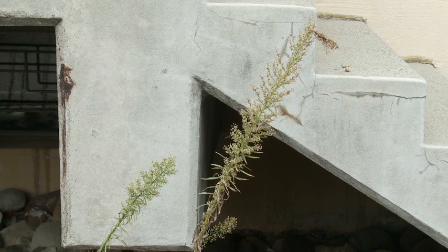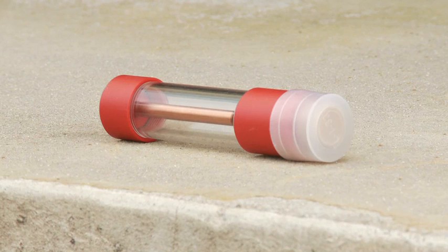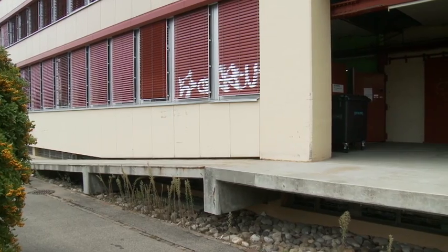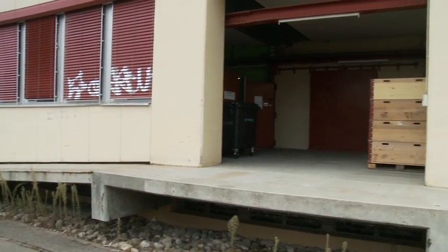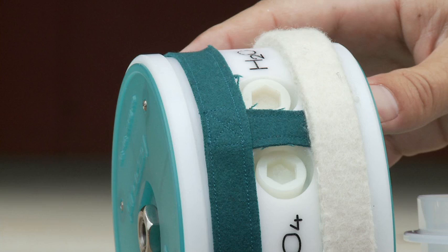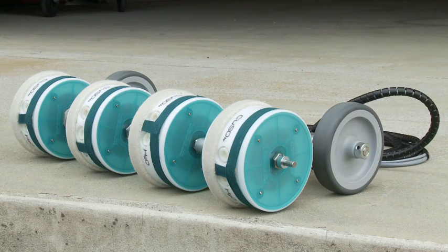Performing a potential field measurement. Depending on the surface under test, it is necessary to choose which type of electrode will be employed. For small areas or areas that are difficult to access, the small and light rod electrode is the most suitable. For more accessible horizontal, vertical or overhead surfaces, it is much faster to use the single wheel electrode. For larger horizontal surfaces, the 4-wheel electrode is recommended for the reason of the significantly faster automatic measurement in a predefined grid.